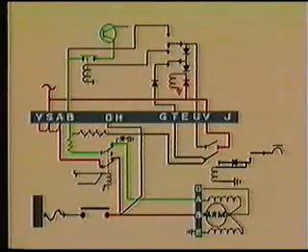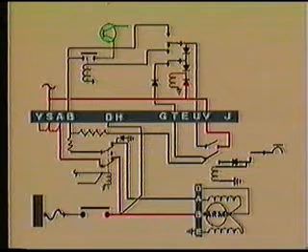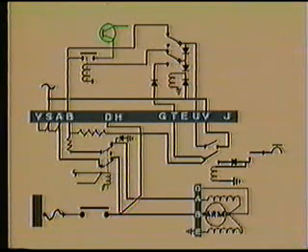During normal operation, the control panel reset relay and the trip relay will both be closed. As you can see from this path, the reset relay is held closed by the output of the B lead of the generator. If the trip relay has opened, the current flow to the A lead will be interrupted, which means there will be no output from the B lead, and the reset relay will be open as well. We are now in a condition where the reset function must be used to bring the generator back online.